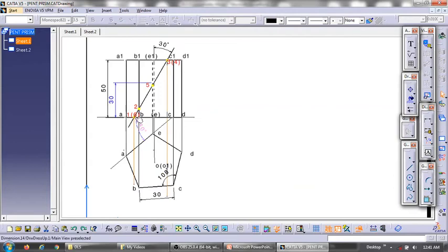So I have done that. I projected 1, 6 onto the top view and 3, 4 onto the top view. So now you need to mark these intersection points in the top view. So we know that 1 is between A and B. So this point is 1. So you can mark that.